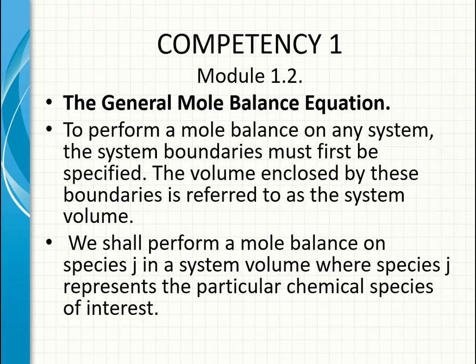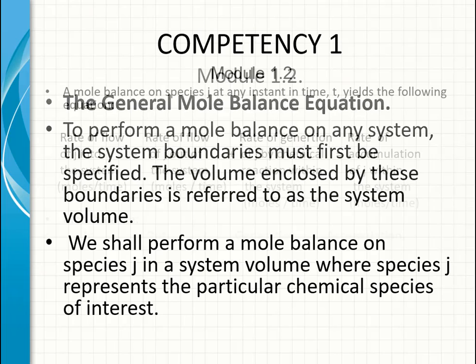The general mole balance equation. To perform a mole balance on any system, the system boundaries must first be specified. The volume enclosed by these boundaries is referred to as the system volume. We shall perform a mole balance on species J in a system volume, where species J represents the particular chemical species of interest.